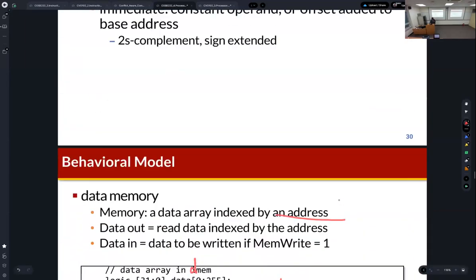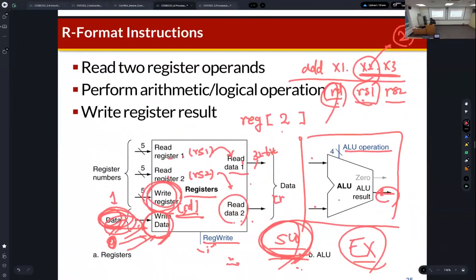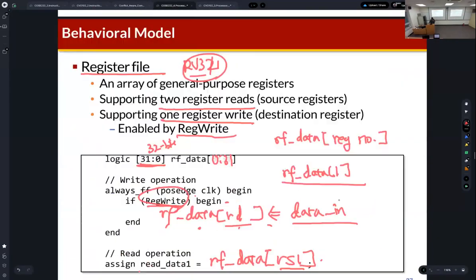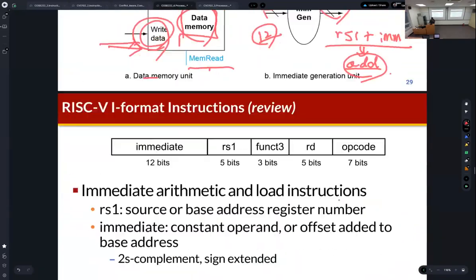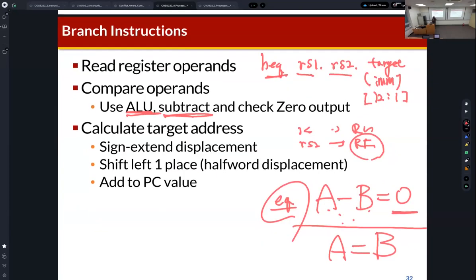If you see the ALU, you can find that the ALU has the 0 port. Why? If the ALU operation mode is subtraction and the result is 0, this means A is equal to B. Suppose this is to support the branch instruction BEQ, then the ALU has the 0 port. It becomes 1 if the ALU result becomes 0.